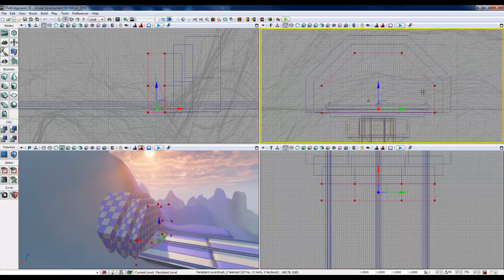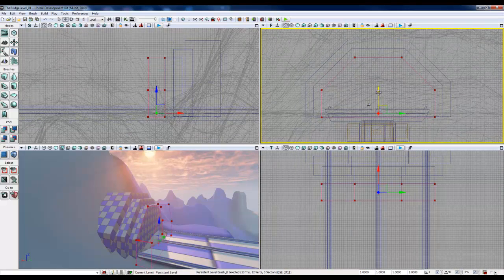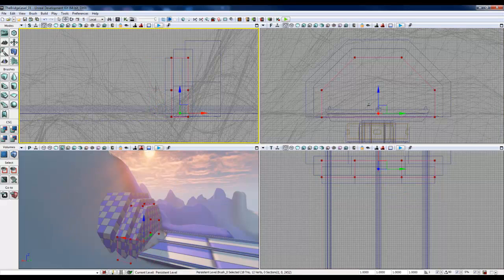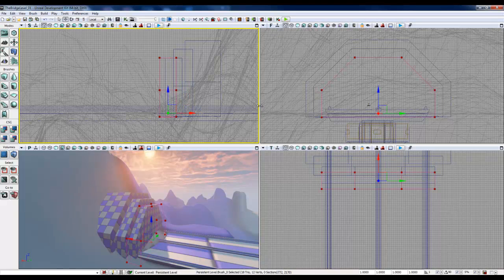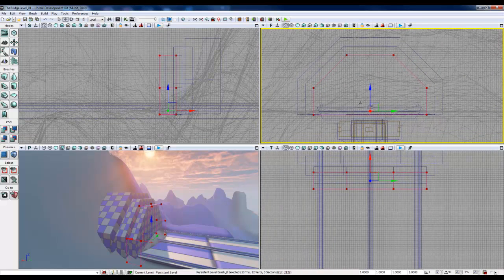And then I also need to make that tunnel. So when you're doing the additive and subtractive CSGs, whatever the last mode was, as in additive or subtractive, is what's going to be in control, basically. So if I were to put a subtractive brush through here and hollow something out, and then I put an additive, what's going to show is the additive, and that subtractive is going to be affected by that additive. But if I do the subtractive last, then that subtractive is what's going to show up.